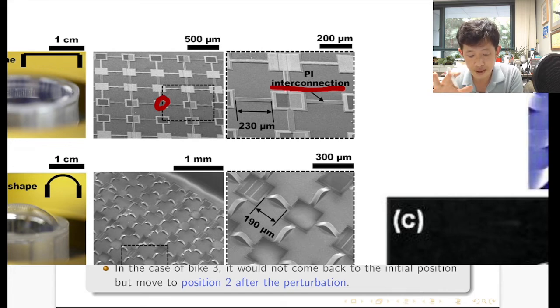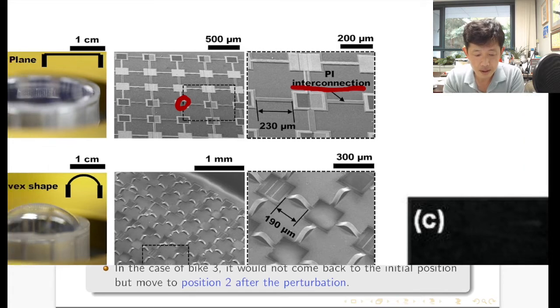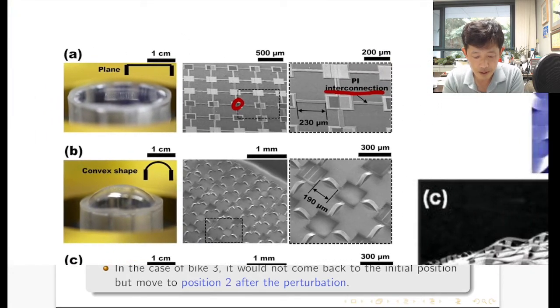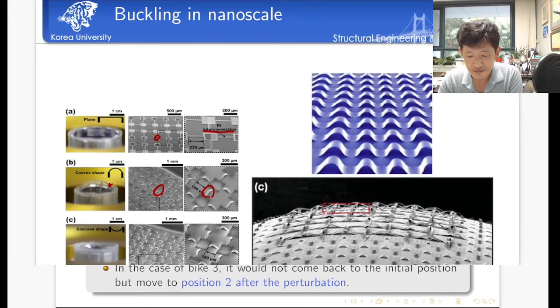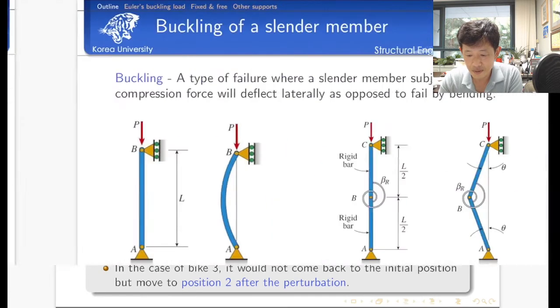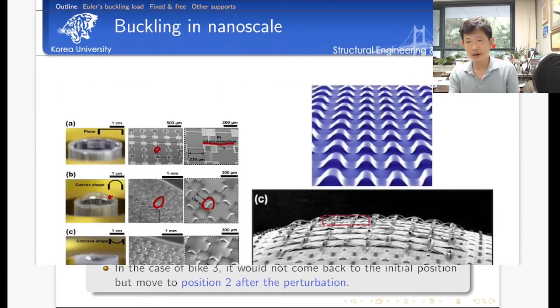stretch the substrate in advance, and they put the sensor array on top of that, and then they release the membrane. Then the membrane shrinks back, and we have these buckled connectors. Because of this buckling, we can provide a limited amount of deformation ability to this device. Okay, still confusing. Let's consider one last example before we talk about the Euler problem.